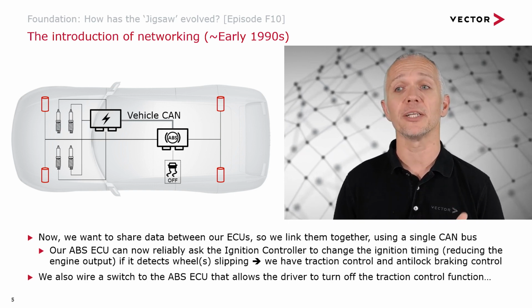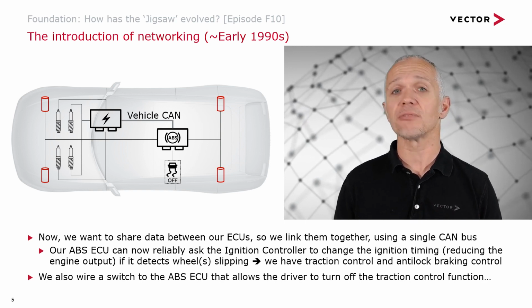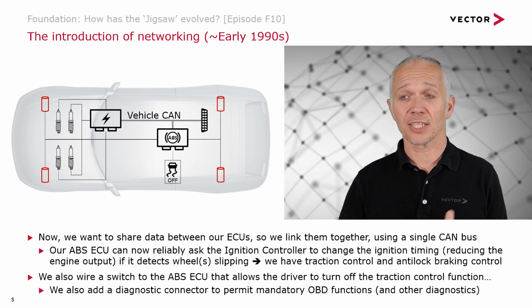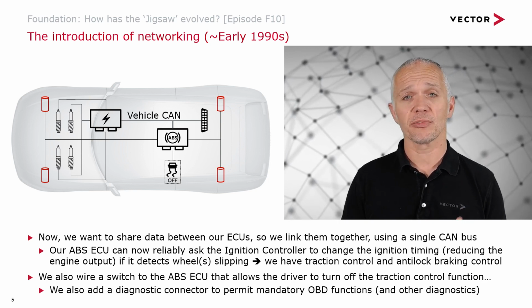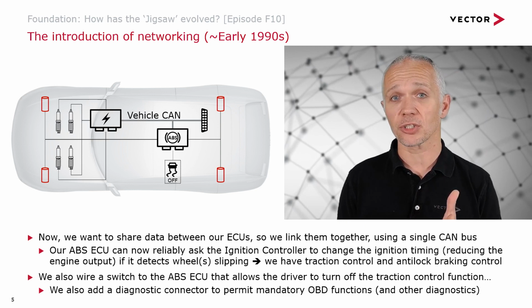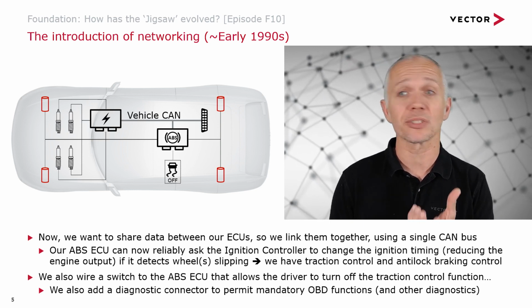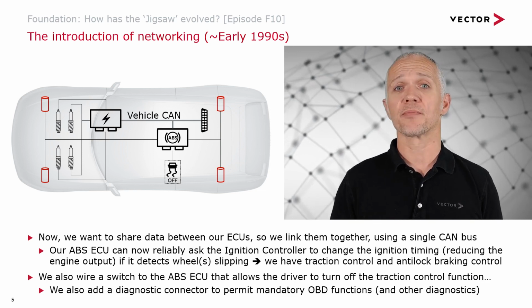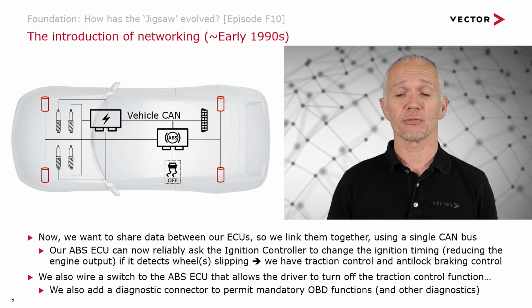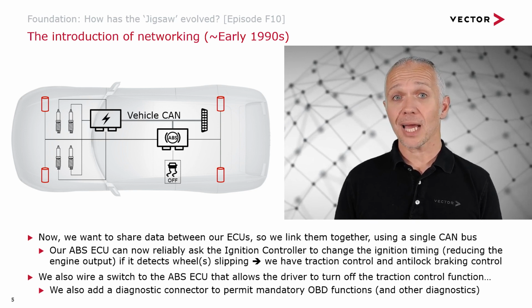So we put in a switch that allows the driver to turn off the traction control function if they so desire. And we also add a diagnostic connector to permit us to perform the mandatory OBD functions that we need to have in the vehicle to be able to sell it, because we have an emissions relevant system here, the ignition control. And we may also want to do other diagnostics, for example, with the ABS ECU, because perhaps, maybe